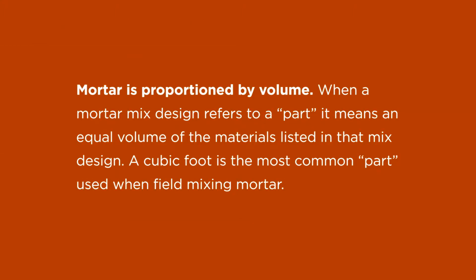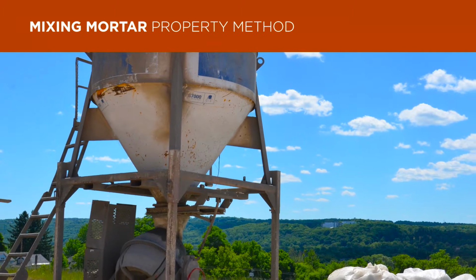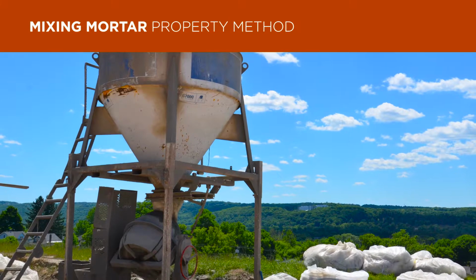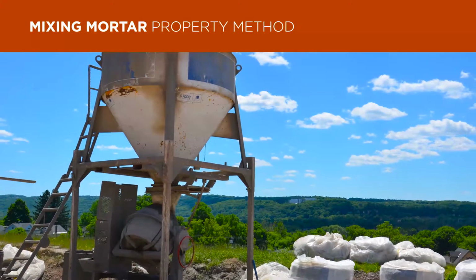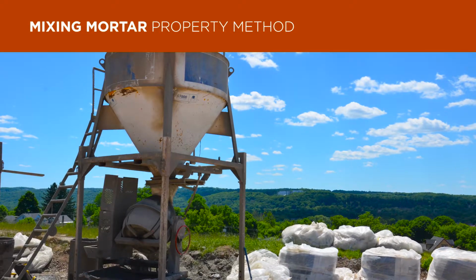Mortar is proportioned by volume. When a mortar mix design refers to a part, it means an equal volume of the materials listed in that mix design. A cubic foot is the most common part used when field mixing mortar. Premix mortars that contain the cementitious materials and aggregates already blended together in the bag can be produced in the factory using the proportion or property methods. Most use the property method and require testing.